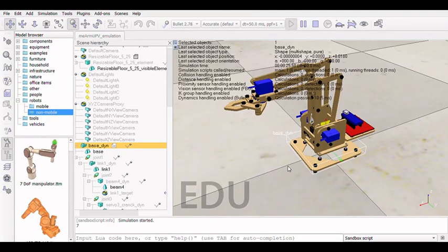We will now see the implementation in the simulation. So first we will see a circle in XY, then in YZ, and finally in XZ. But we have to remember that in XY it's not a perfect circle, but instead 2 arcs that may look like an ellipse. And this is because those points were not chosen using the Matlab function, and therefore they do not describe a perfect circle.